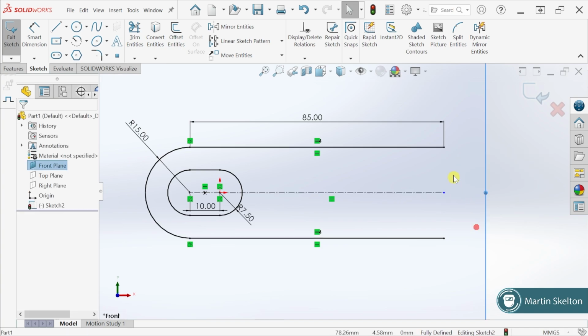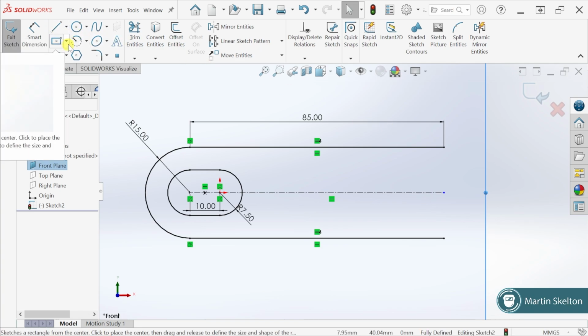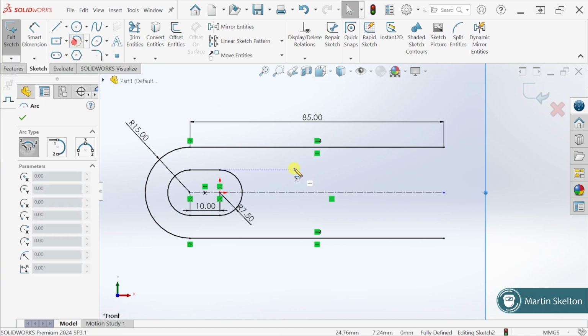It doesn't lock into anything. Well, why isn't my sketch underdefined? My sketch isn't underdefined because, remember, the software doesn't take blue or undefined construction lines as part of the model. So it doesn't matter about construction lines being underdefined, or usually it doesn't matter. It only matters about the heavy dark outlines. I'm going to take my full solid line again. No, I'm not actually. I'm going to take my arc.